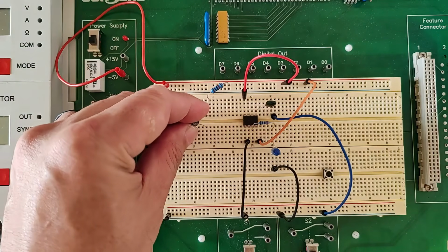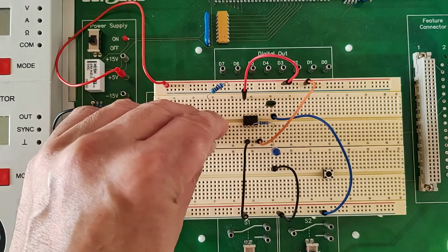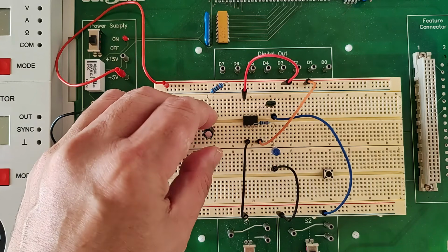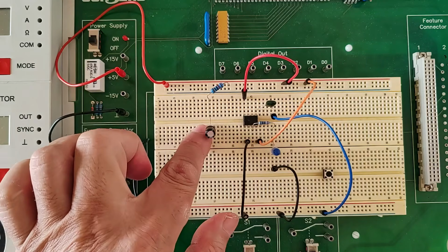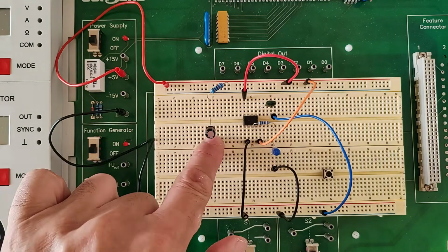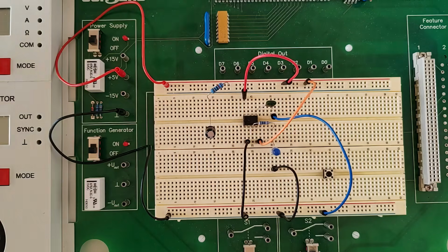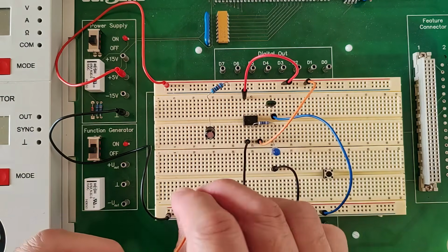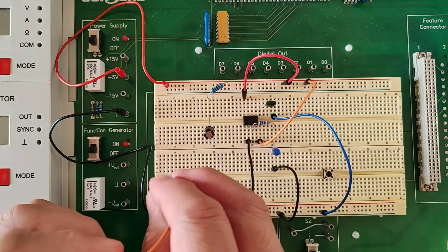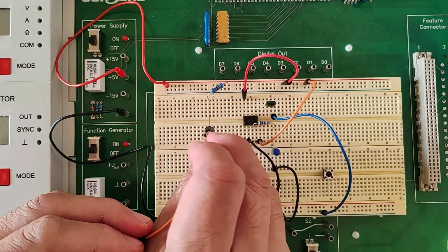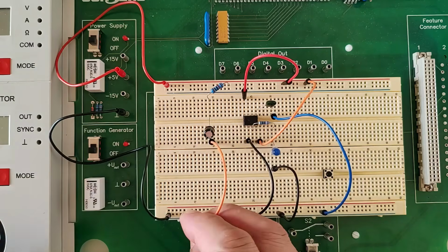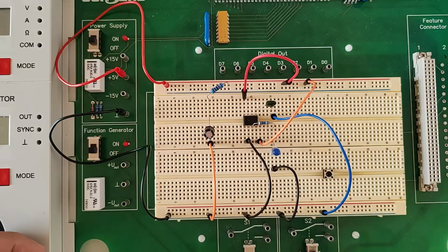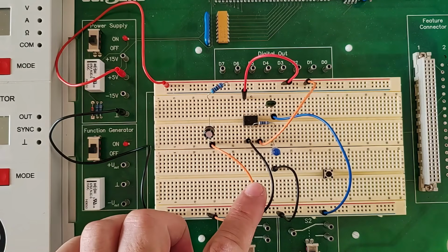Let's do that now. Okay, so capacitor connected to the resistor here, longer leg. There. The shorter leg connected on the other side. See here. And this leg, the negative terminal of that capacitor, the 47 microfarad capacitor, will have to be connected to ground. Let's do that now. So capacitor negative connected to ground. See here.